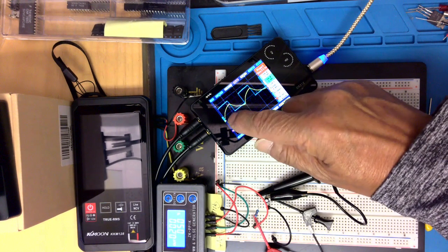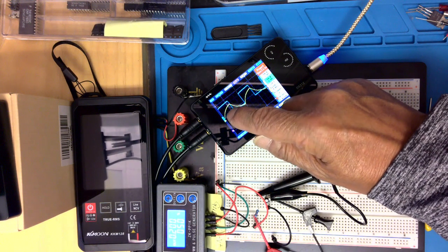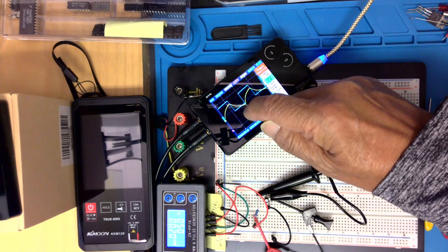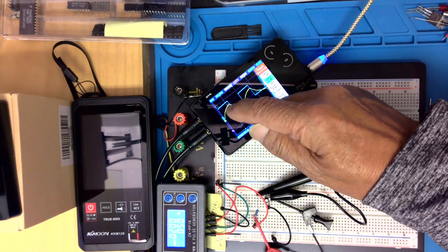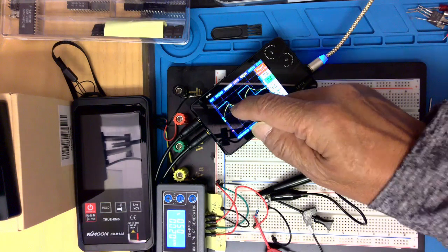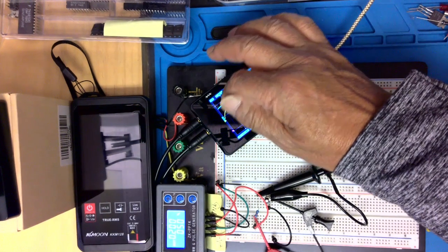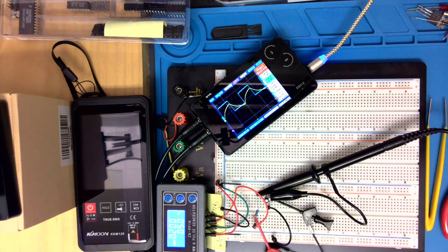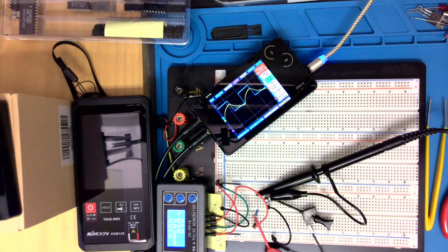The voltage gradually goes up and comes down, but this coming down speed depends on this reference voltage. The reference voltage is programmable, and that's the way they make a programmable timer. Okay, we're going to do that very soon.